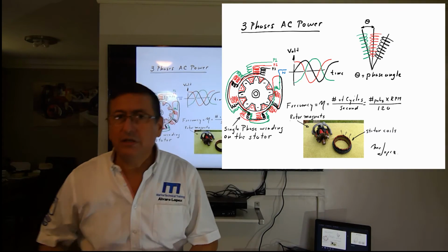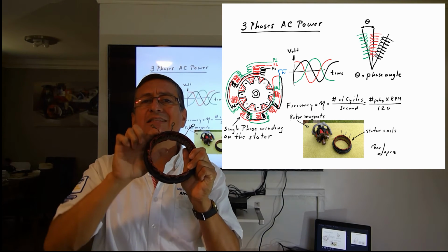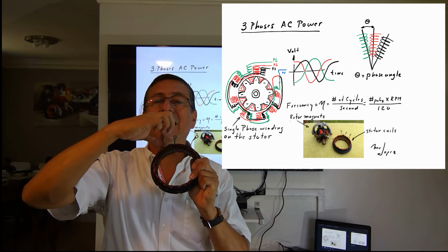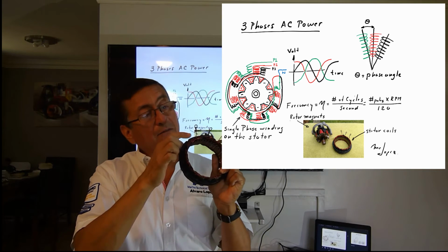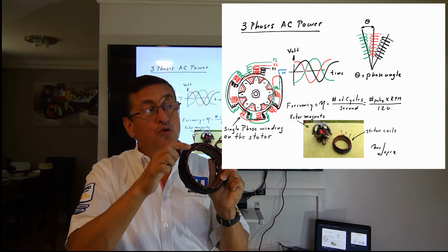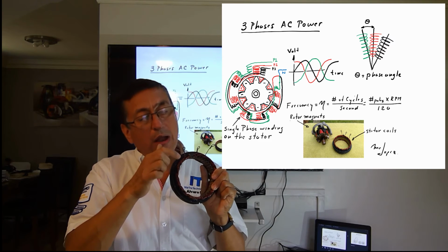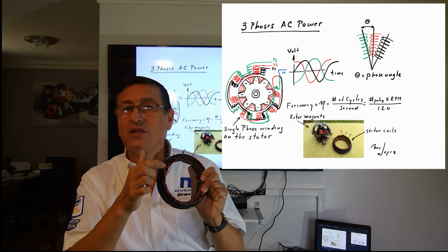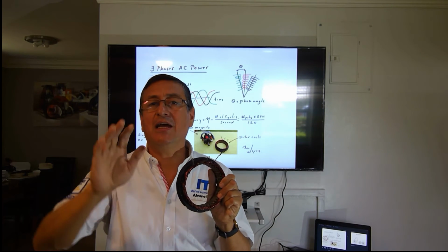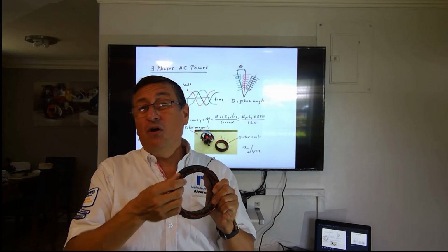Why? Because the wire in each coil is covered with a special resin, a special varnish. That resin is a high temperature resin that avoids that one wire touches the other wire. Those wires are isolated. Those wires never touch. When one of those wires touches the other one, the stator is in short, and the output voltage is 0.